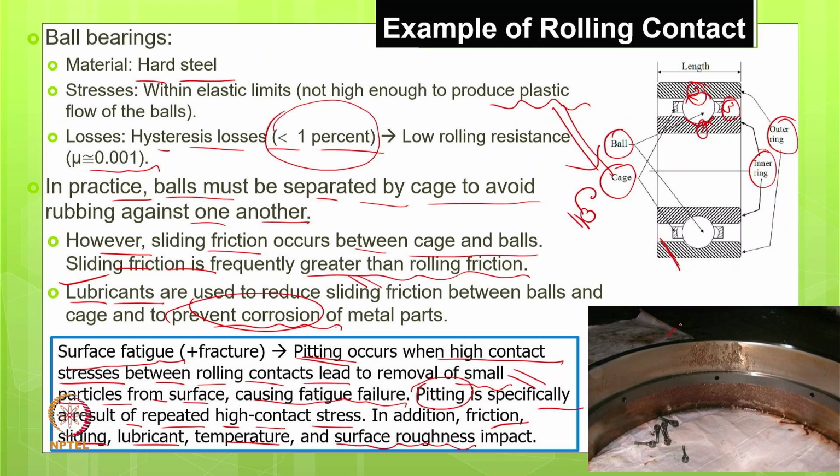Now, this picture shows one rolling element bearing which I analyzed. You are able to see a number of pits. This outer race has already sustained 40,000 operating hours. That's why the pitting has happened and is concentrated. This is only one portion of the bearing, and if you rotate the bearing further, it may sustain maybe 500 more hours.